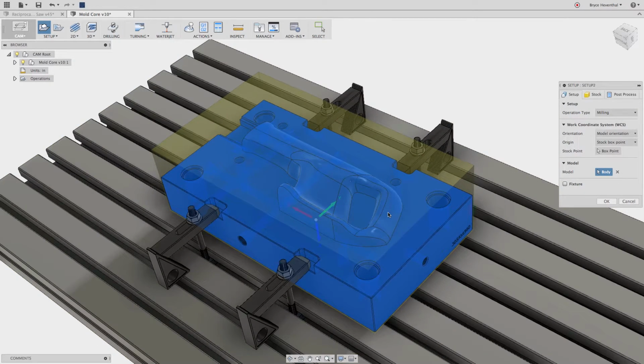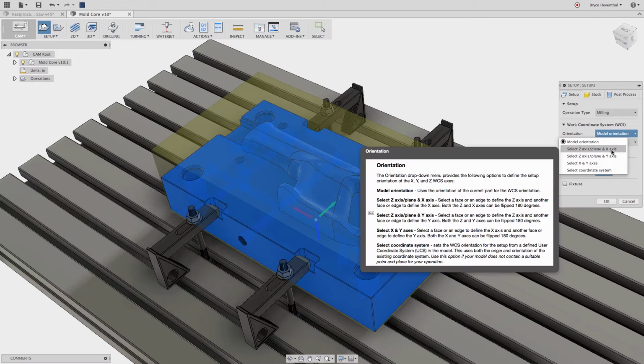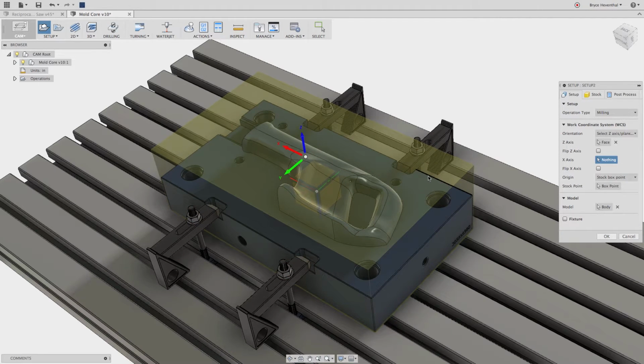We will orient the Z-axis and pick the location for the pickup of our part. We will use this corner to probe when locating our part in our machine. Normally we'd want to take this time to measure our stock with calipers, and we can input these values on the stock tab to ensure our part is cut to the correct dimensions.